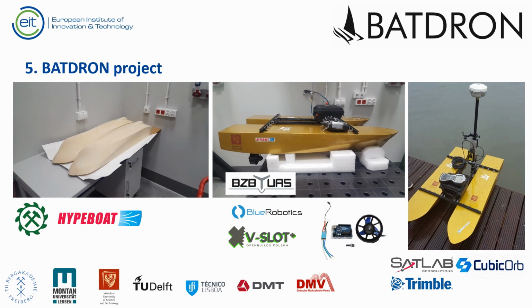The autopilot module is based on the ArduPilot Pixhawk, integrated with an Arduino board with a Graupner RC radio. The boat is powered by a Tattu 12,000 mAh battery that provides power to the platform for about 2.5 hours. The first test of the Batdron project was held in October 2019 in West Boulevard.